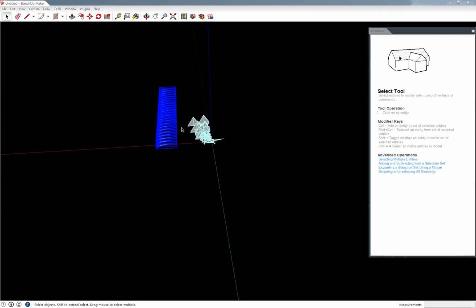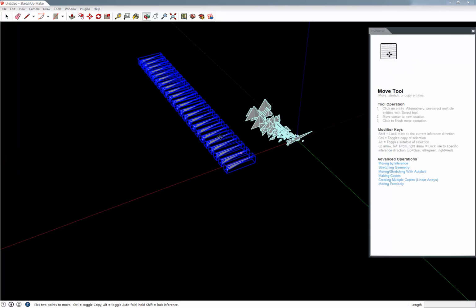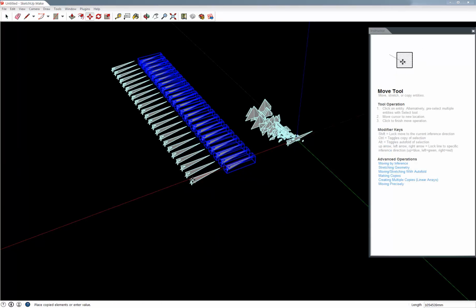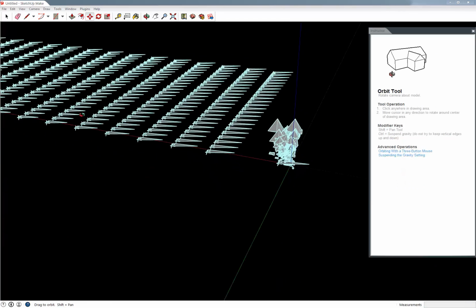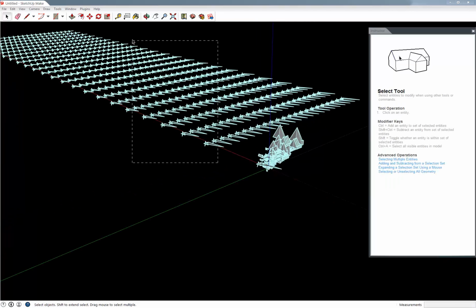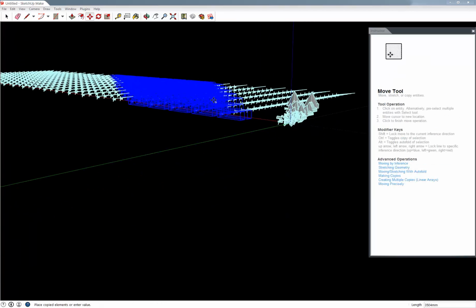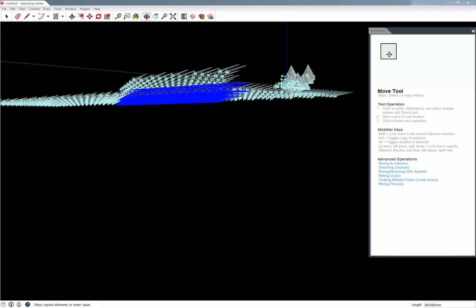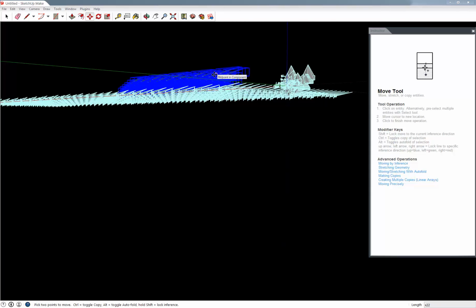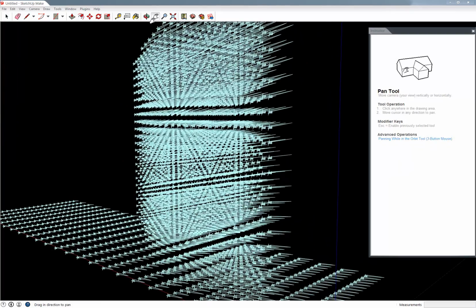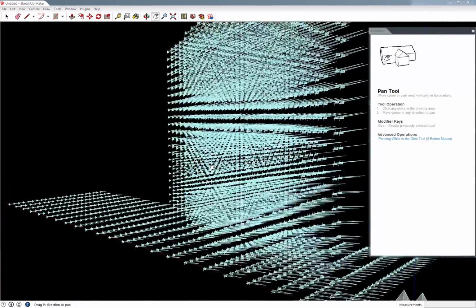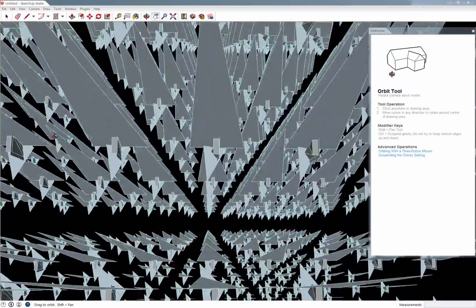So you can do that with any selection. So now I'm selecting the whole lot again. I'll copy them this way, times 22. Now I've got this big matrix of them, and now I want to copy them up as well. So I'll copy them up. Oh, getting a wee bit laggy now. So I'll click there, times 22, enter. Another cool tool is the hand tool up here, where you press H, you can pan around. So look at that.